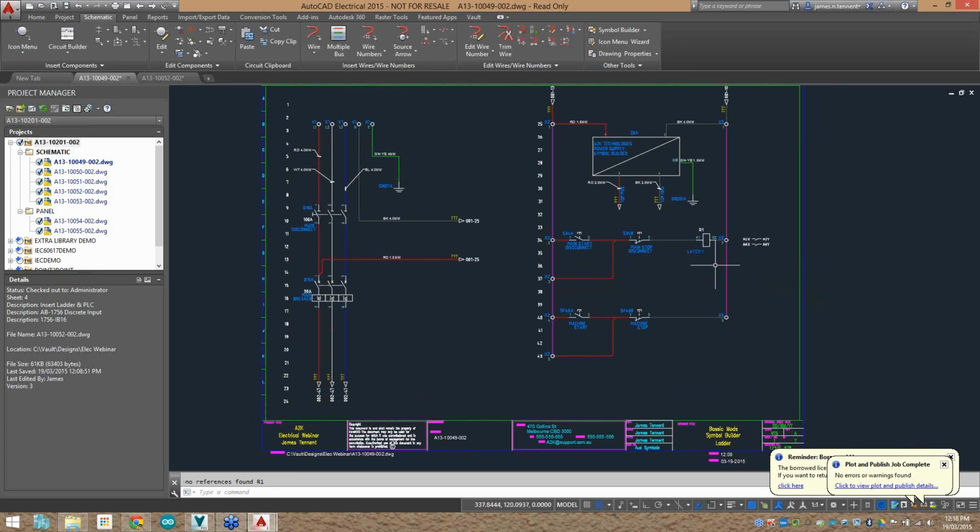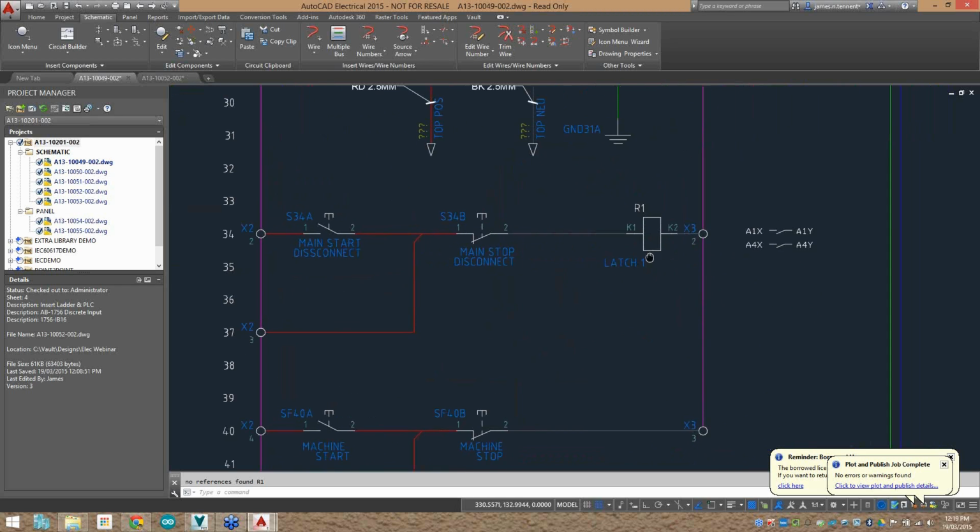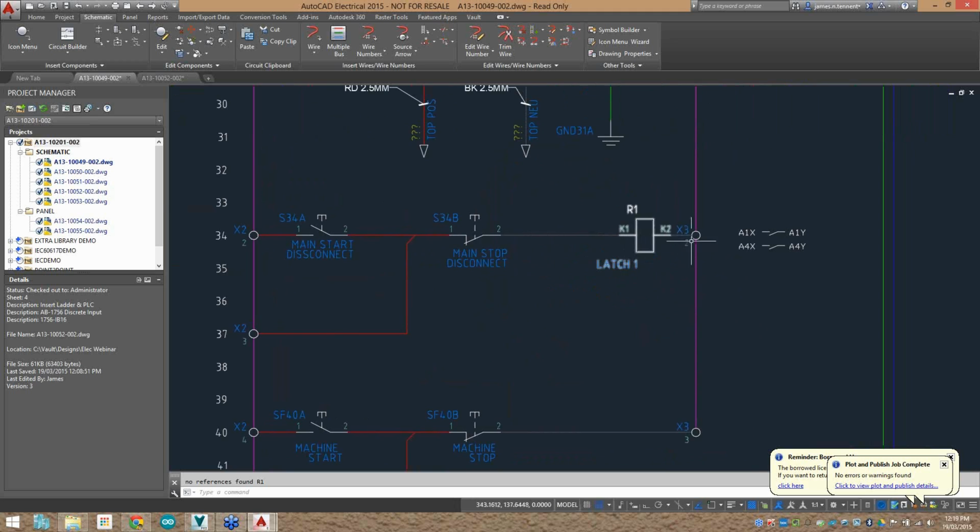So let's go ahead and do that. Once I've inserted that, you can see the cross-referencing table has been inserted. All the information's been put in there, and so on and so forth. This information here is all attributed information. And if I wanted to modify any of the attribute locations, I can go and move any of that attribute information. Let me just try that again without snap turned on. Let's say move, and let's put it across.